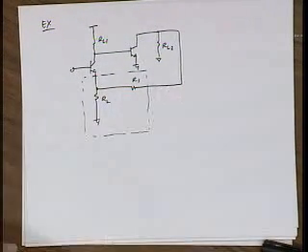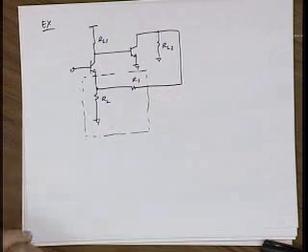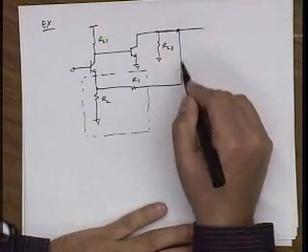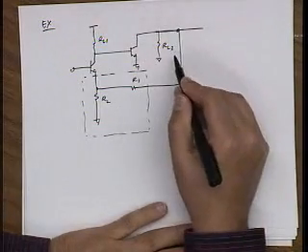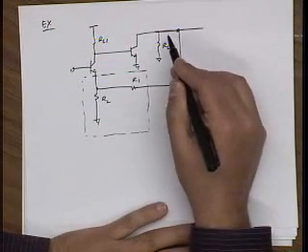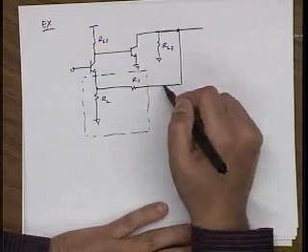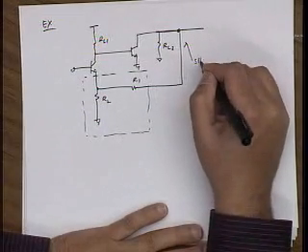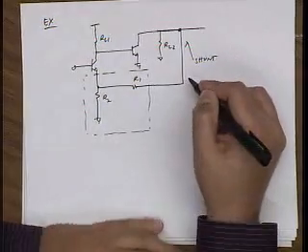So don't feel bad if it's not obvious. First of all, that's the nice thing about the loop gain approach. You don't really need to know what's going on. You just calculate the loop gain, and that is actually the loop gain. But remember, here I'm taking a shunt connection, right? So think about it this way. It's summing currents with the output. That means it's actually sampling a voltage. So a shunt connection here is sampling a voltage, right?